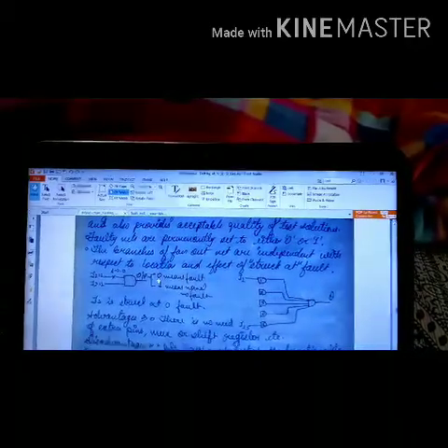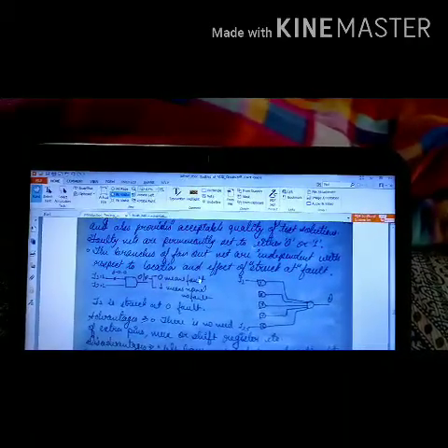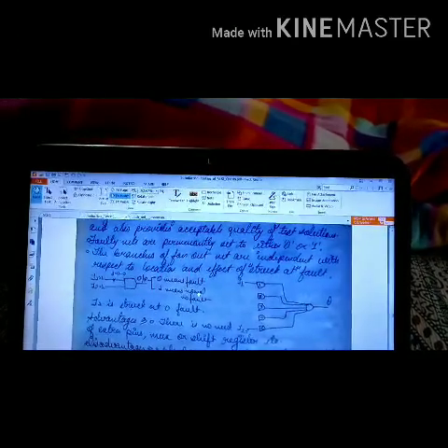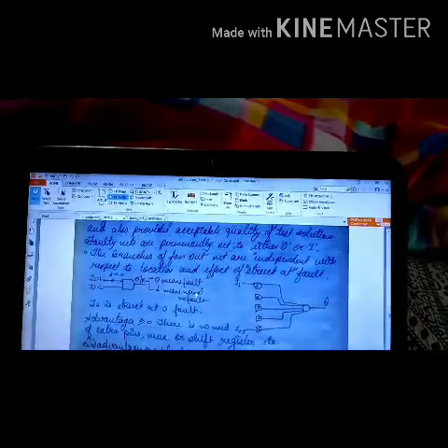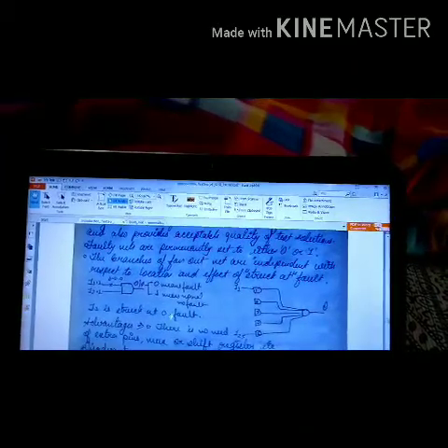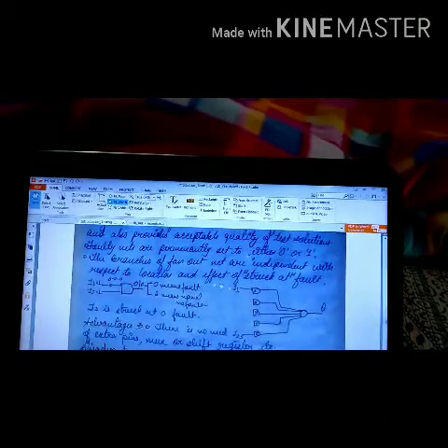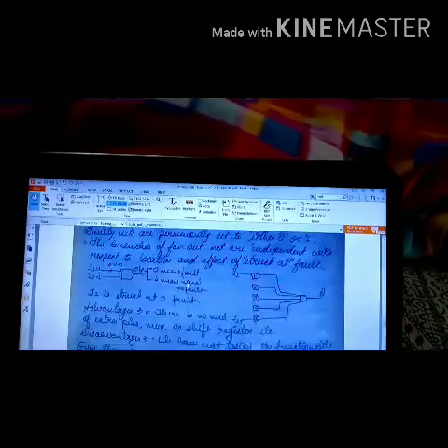So whenever I get an output as 0, it means that a fault has been encountered, and if I get an output as 1, it means that it is normal and there is no fault. So I1 was stuck at 0 fault. In a similar way, multiple AND gates can be checked for such types of faults.